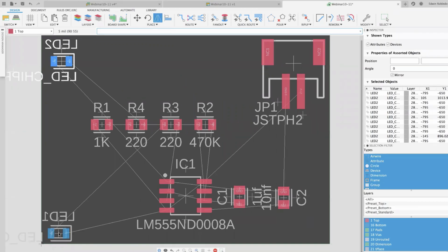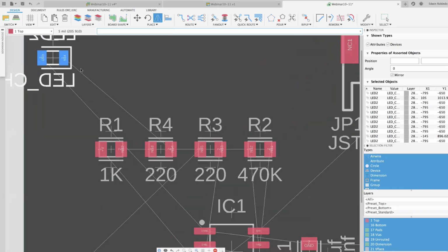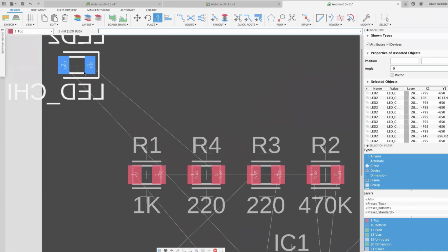As you can see, it automatically activated, and I click on the component. Please notice that the pads, the landings where the components get soldered onto the circuit board, turned blue. This is an indicator letting you know that this component is on the opposite side of the board. In this reference, we use the color blue to refer to the bottom side of the board, while we use red for the top side of the board. That's how you know the difference between one layer and the other.